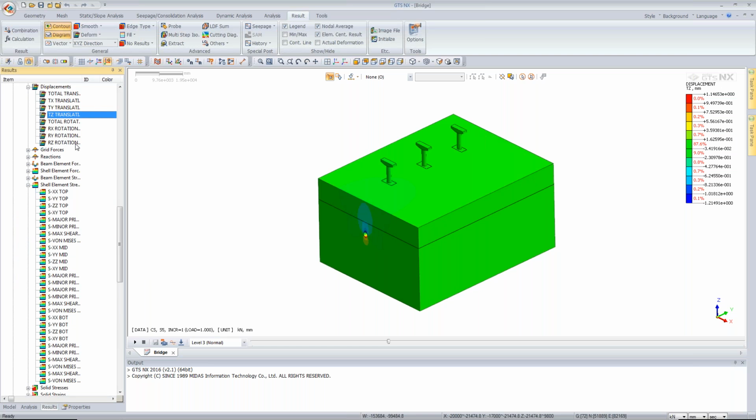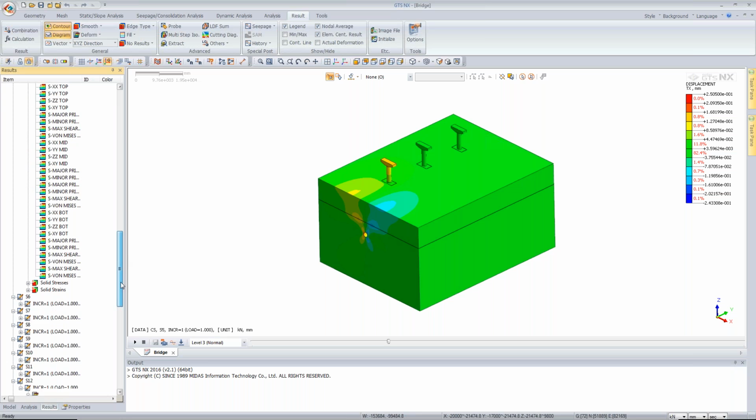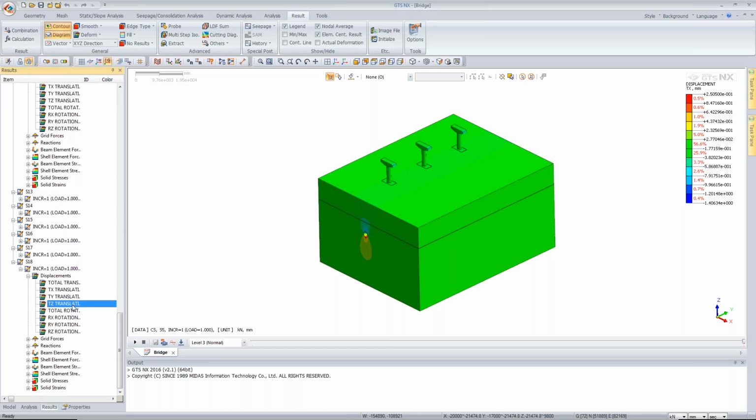This was a simple model where we have a circular tunnel and a soil layer with a high E value. We want to see with each stage how exactly, if there is some existing structure, in this case a bridge pier foundation, but maybe some building, and you are performing the tunnel, how it can affect it in terms of settlement and stresses in the piles.